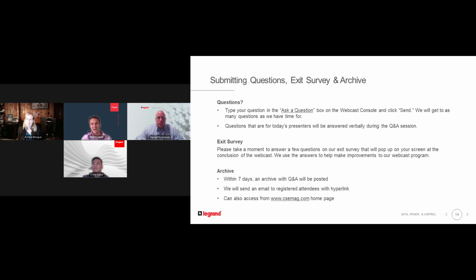Even with Starline, our instructions will say, hey, every 10 feet, you want to have a support. And I've personally been on sites where I walk in there and they're on 30-foot centers. And they have 20-foot sections of busway hanging in the air with a large bow in them, right? And then surprisingly, they're asking why they're not working, right? So that's typically in industrial facilities. We see that in things like automotive factories, just due to the spacing.